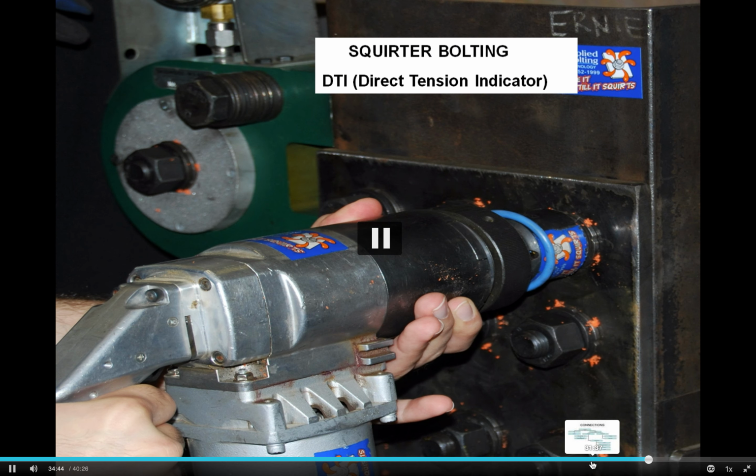We're using a lot of indicators now because there have been a lot of failures where the crews doing the work under-tension these nuts, and halfway through construction, you're hearing plink, plink, plink coming down. From vibration in the building, these weren't secure, and they start to fall off, and then you have to go find out where it is.